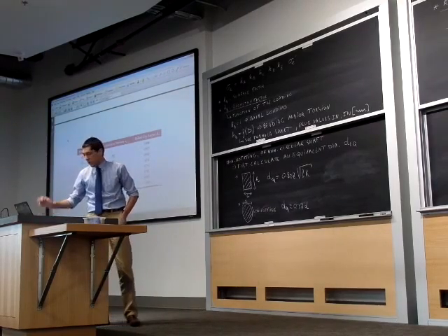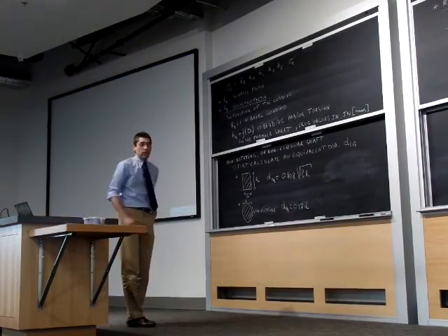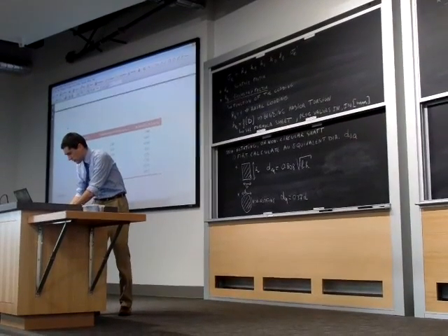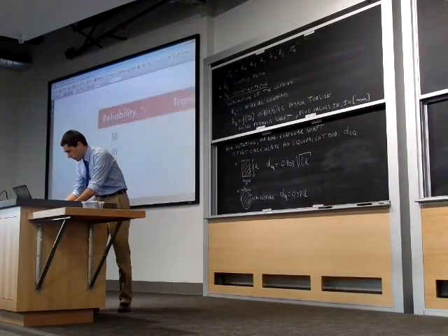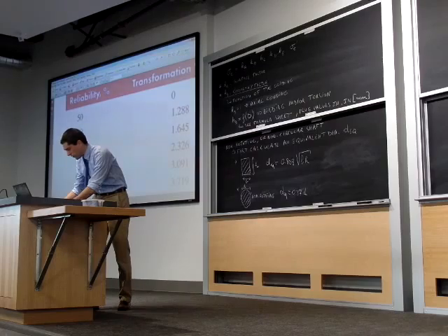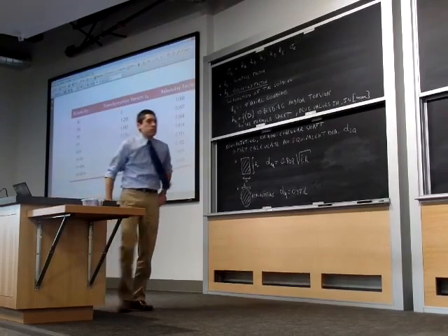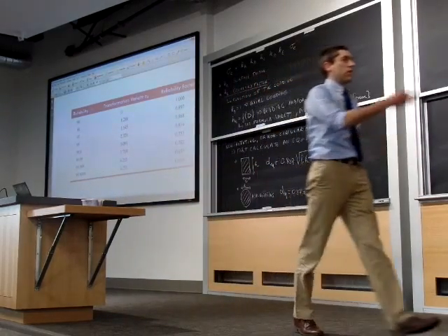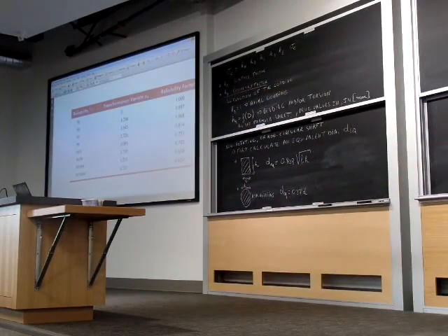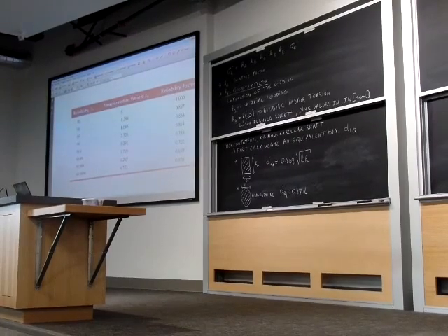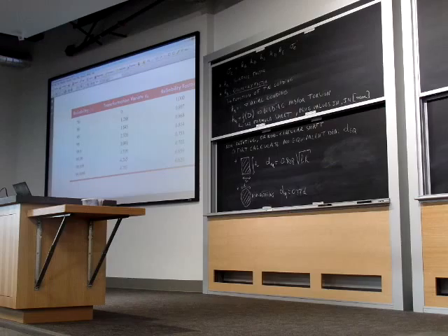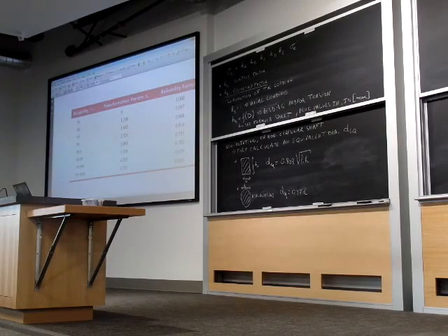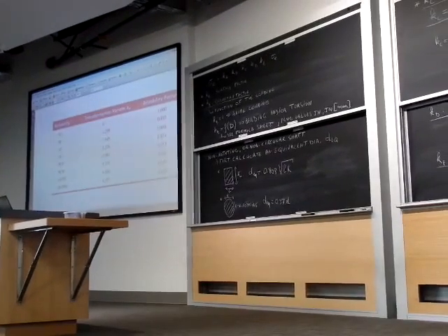So you can say, I want a reliability of 50%, and that of course is going to give you the thinnest structures. Say if you want to have Ke equal to 1, then this corresponds according to this table with a reliability of 50%, and then you see that your reliability factor decreases with increasing required reliability. What does that mean?